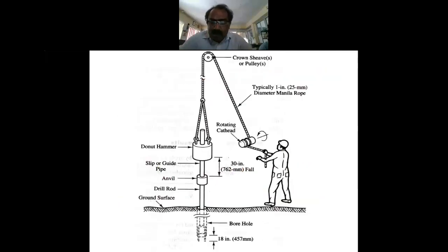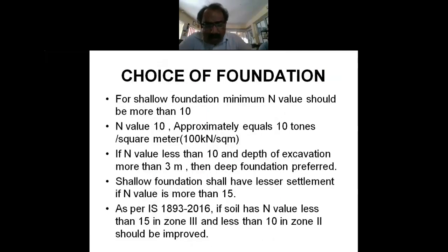So how to choose the foundation depth: don't go below 3 meters, because the normal Indian human height is 1.6 to 1.65 meters. If anything happens, if you raise the hand, it is not more than 2 meters, so inside the pit you have to rescue the people. So it is not advisable to go beyond 2 meters at least, but the maximum is 3 meters. If the N value may be 40 at 3.5 meters, don't go to 3.5 without proper armor or proper protection or shoring system.